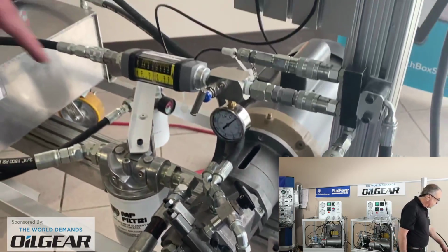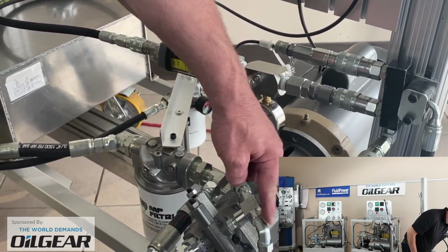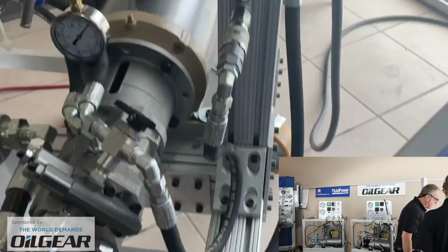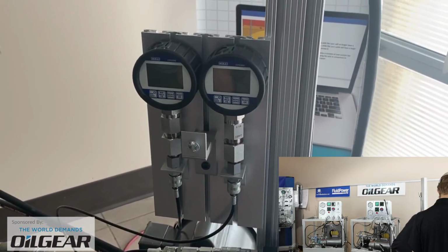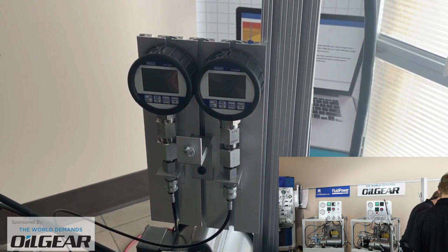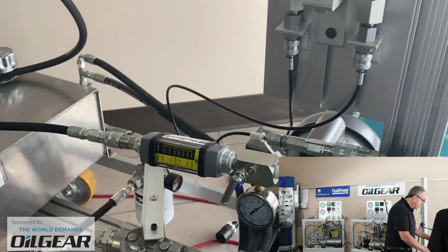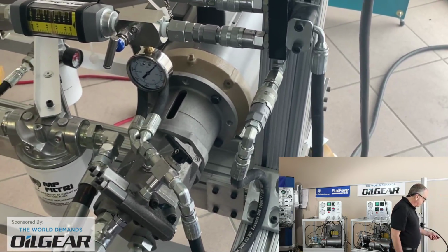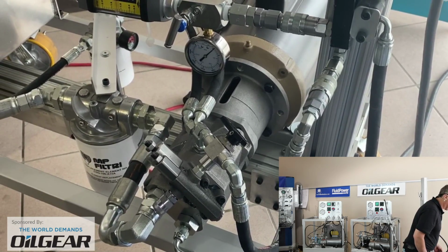But in this particular case, with the control hose coming out of the DFR style compensator and the valve set to route that compensator right into the pump's outlet pressure, that basically knocks out the flow compensator, the load sense compensator as it's sometimes called. So right now, the way we've got it configured, we really only have the single pressure compensator adjustment.